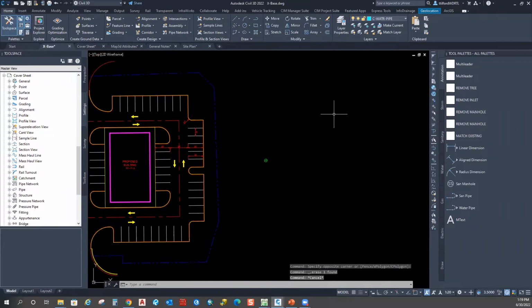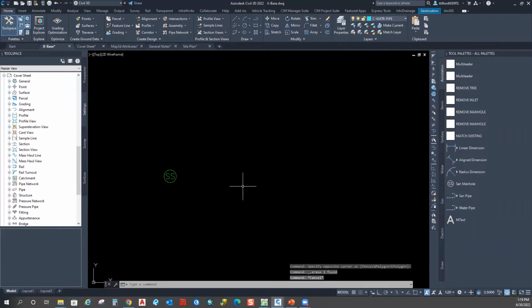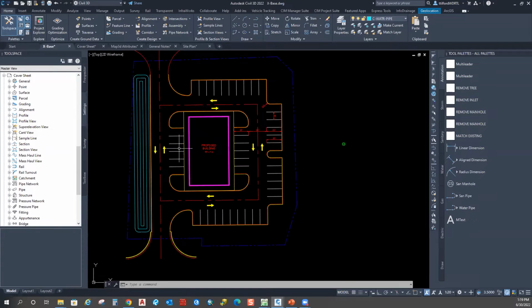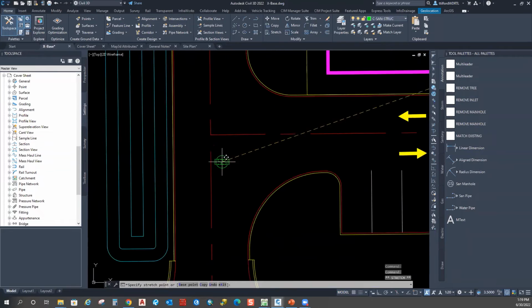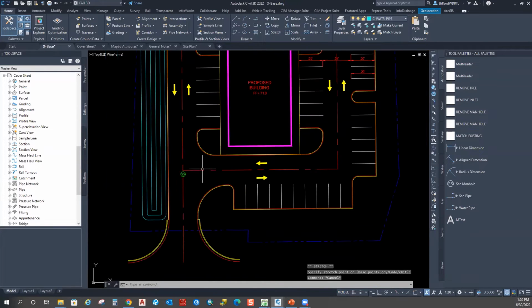Well, I've got a manhole here, and I was thinking about how I could use the Data Wizard to get some estimating done. This is a new little site plan that I had. Let's say I have this sanitary sewer run coming in here, and I created some pipe runs, a sanitary pipe, manhole, and a sand pipe that I dragged over here and modified in my palette.